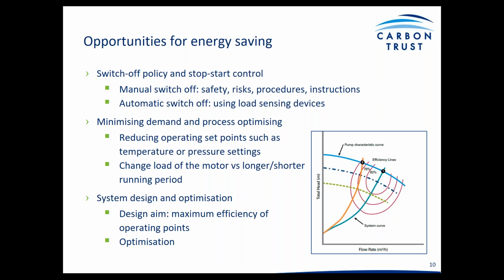Some other times it's sensible to use automatic switch-off devices to sense the load in a particular application, and then manage the motor operating hours by default using those controls. A typical example could be timers on ventilation, temperature controls, or, on pumping systems, pressure controls.